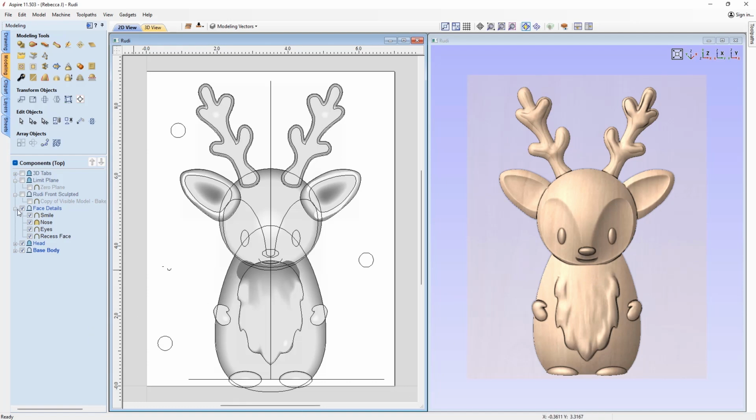Okay, so with all of that, I used my favourite tool in the modelling toolbox, which is create a component from a visible model. What that does is it basically takes a photograph of our composite model and creates a single model based on everything that it can see in our composite model.